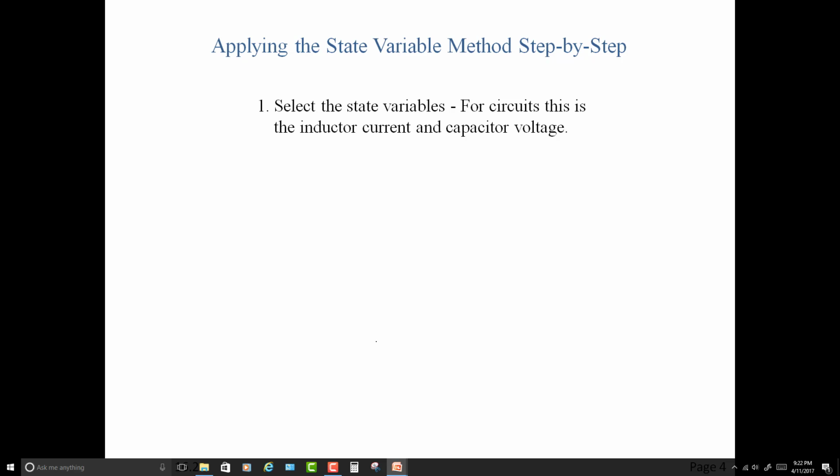So ours are going to involve circuits where there's an inductor and/or a capacitor. All right, in mechanical systems, you're just looking for things that likewise relate to variables, like in our case, current and voltage, relate to variables by a differential form. And that's a way of helping you select what are the state variables. For us, we use really basic stuff, blocking and tackling, Kirchhoff's voltage law, Kirchhoff's current law. Why is that? Well, we want that set of equations.